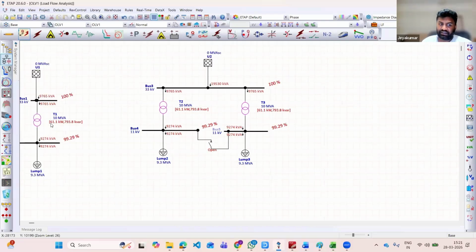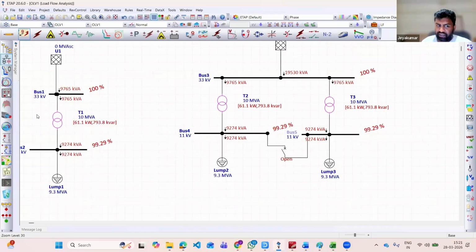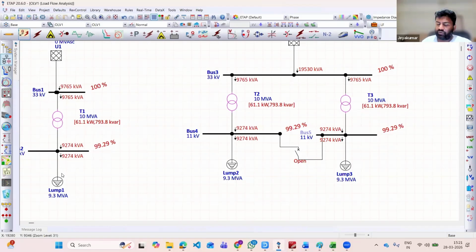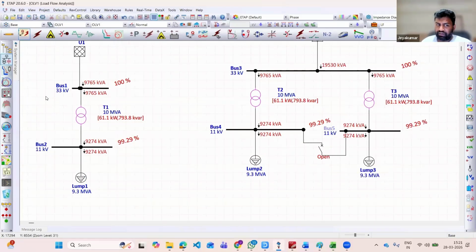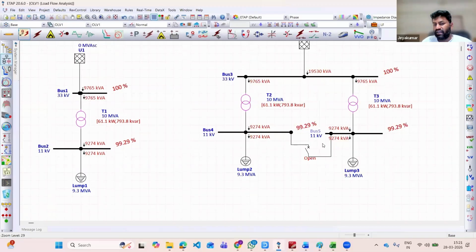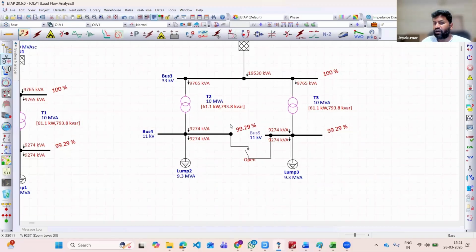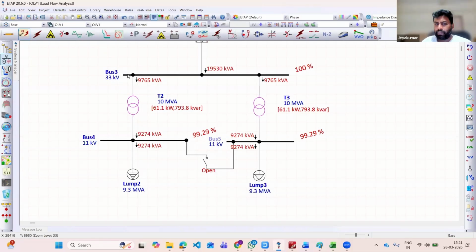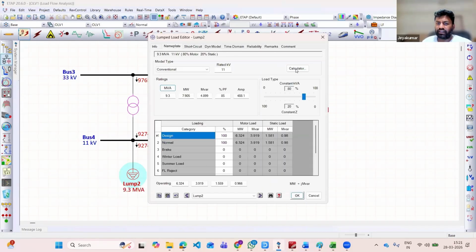See, in this there is a risk. What if you have to take the transformer out for maintenance? Then you have to switch off the load, or you have to have the DG set or something, that's the only option. But here there is an option: you can have one more transformer so that your loads can be put like that.